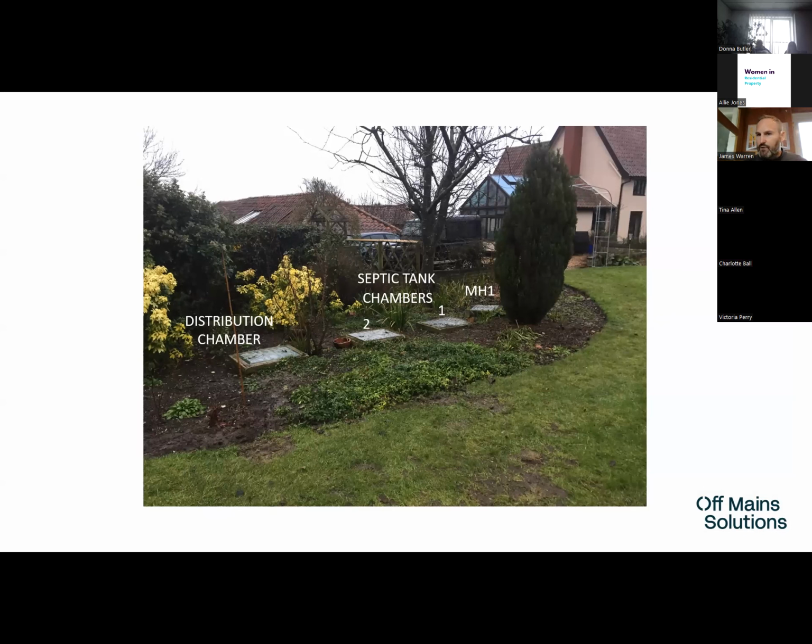So if ever anyone sees a photograph of a property, maybe with some site details, and there's a series of manholes in a row like this, you can tell immediately it's going to be an off-mains drainage system, simply because you only need a manhole when there is a connection coming in from the side, or if the pipework changes direction greater than 45 degrees. So to have 4 manholes in a row in this sequence, if it was going to a normal sewerage system, a main sewer, it would be a crazy dogleg system. The pipework would be going crazy in between those manholes. It makes no sense.